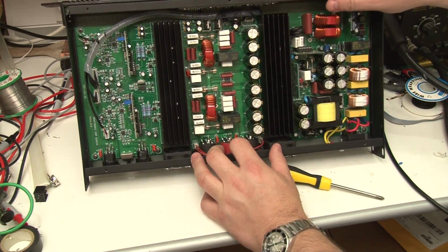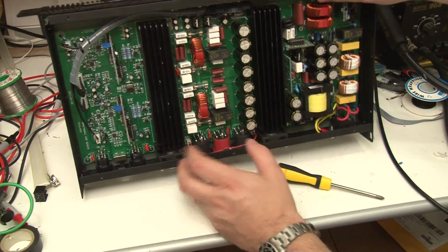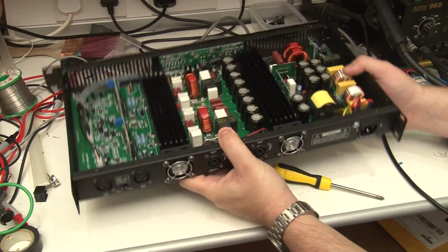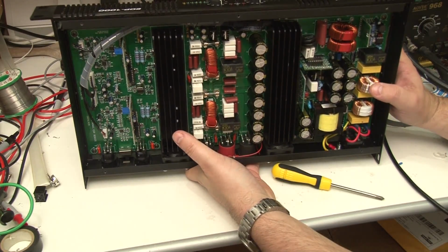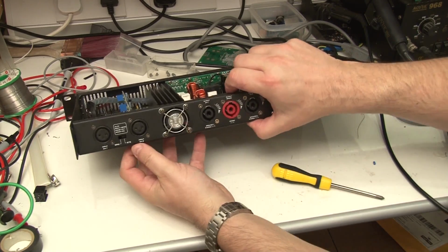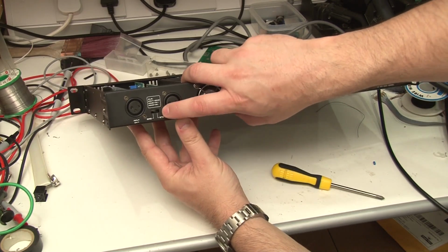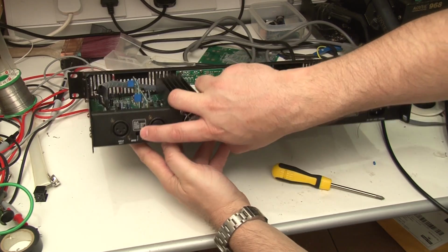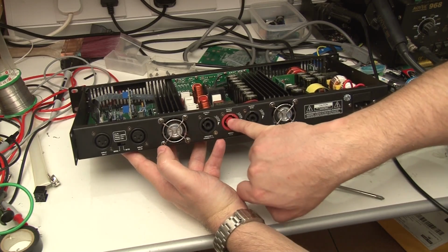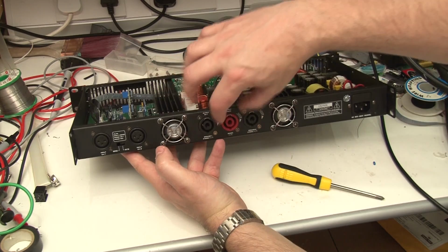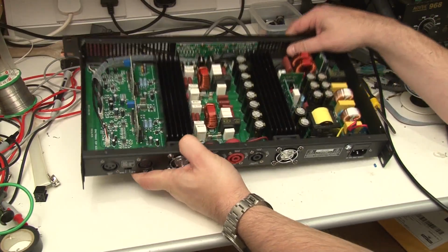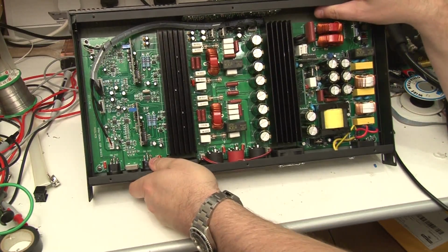Okay, so I don't think there's much else to say about that. One other thing worth mentioning is just like a conventional amplifier, of course, you can run these things in bridge mode. So this amplifier can either be 2 times 550 watts, or it can in fact be 1 times 1,000 watts. That's what they rate it at. So you'll find over here you've got a switch which sets it either to bridge mode or stereo mode. If you switch it to bridge mode, you put the input in one here, and connect the single output speaker to this connection here, which is effectively the positive out, wired to the positive terminal on each of these sides. So a Class D configuration can also be used as a bridged amplifier if required.